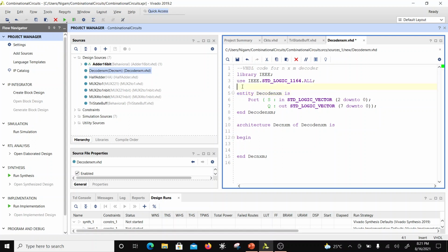The selected assignment or any conditional assignment is not going to work here, because somewhere you have to make all the lines except the one as 0. So you cannot have two concurrent assignments to the same bit. So as you go ahead, you will know what I mean by that, right?